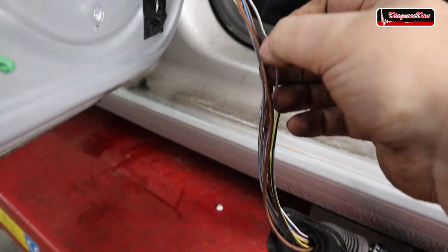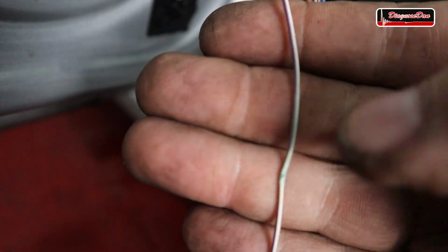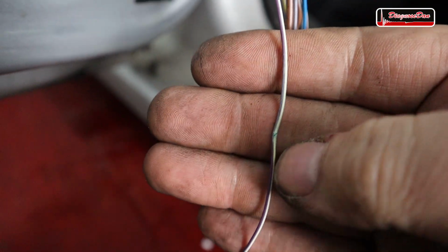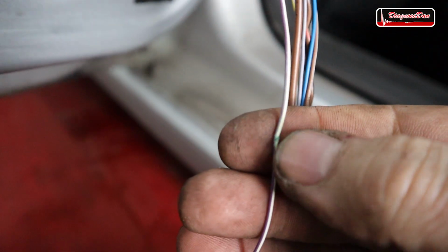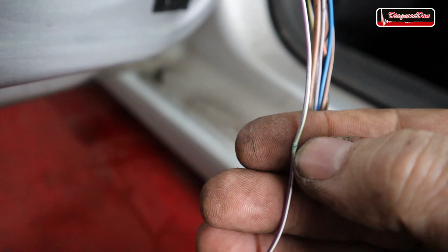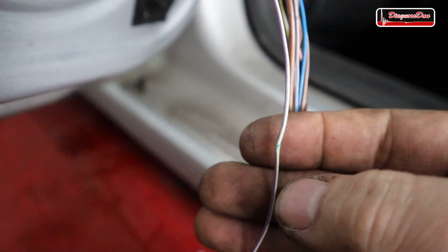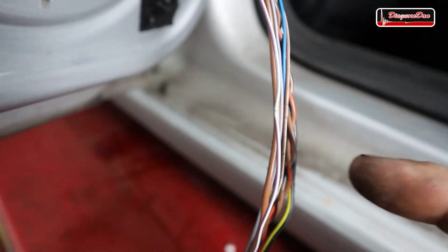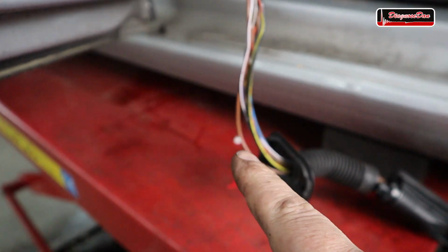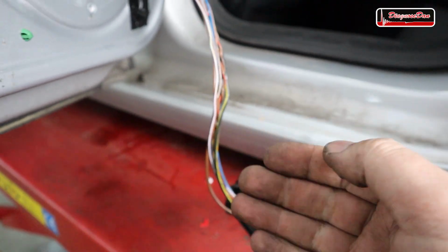This is the purple and white wire, and when we look closely to this spot right here, you can see a tiny trace of green crusties right there. Now that wire is probably rotten through right there, so it is broken, but it's still being held together. Now you can see that it's quite far from the hinge area where you would expect something like this.